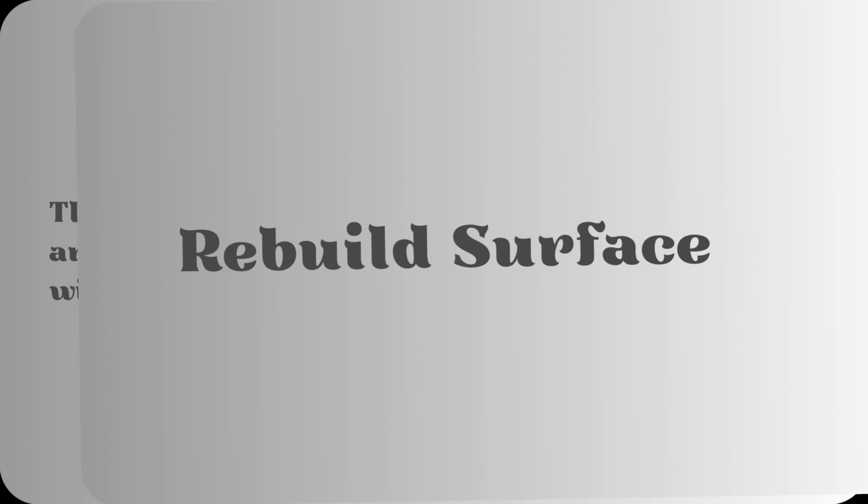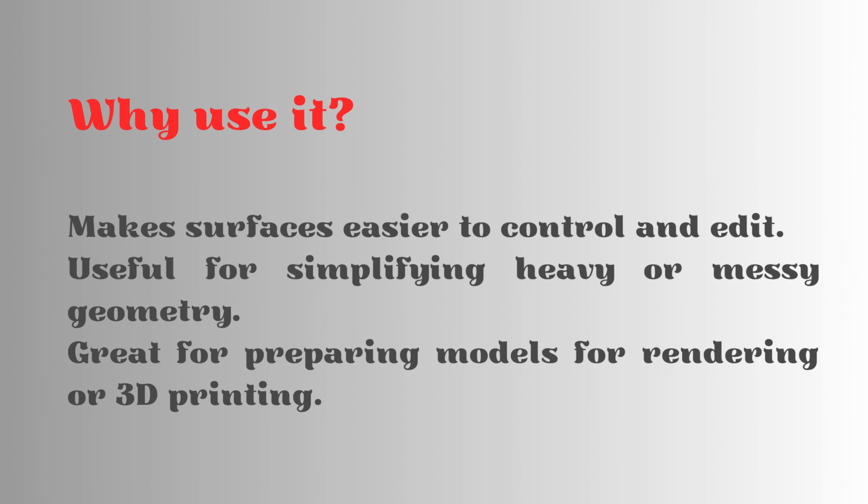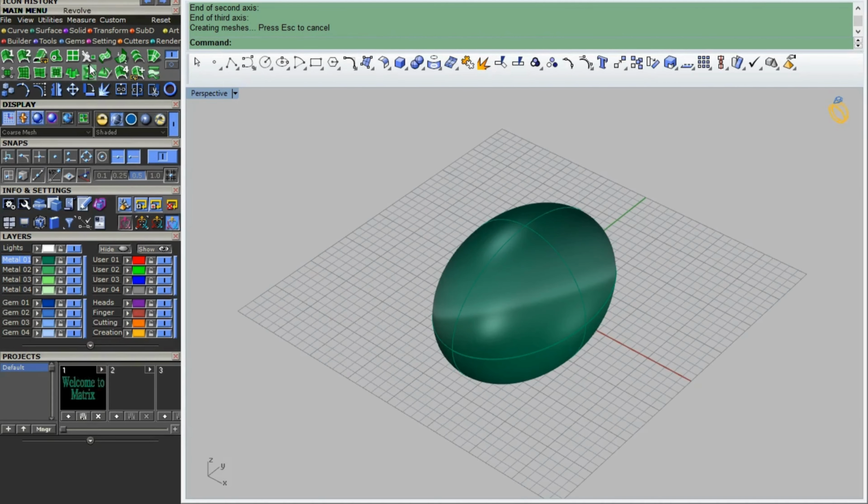Rebuild surface. The Rebuild Surface tool allows you to redefine and simplify an existing surface in Rhino without drastically changing its shape. Makes surfaces easier to control and edit. Useful for simplifying heavy or messy geometry. Great for preparing models for rendering or 3D printing.